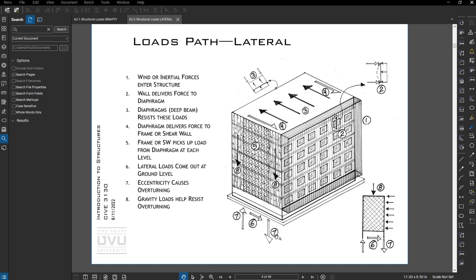So when I detail or design things, like say a wood building, I'll go from a wood diaphragm to a nail to another piece of wood to maybe a metal clip to another nail to another piece of wood, then back into the wall sheathing. It gets that particular. And if you are that particular about it, your buildings are going to be fantastic and robust, which is exactly what you get hired to do.